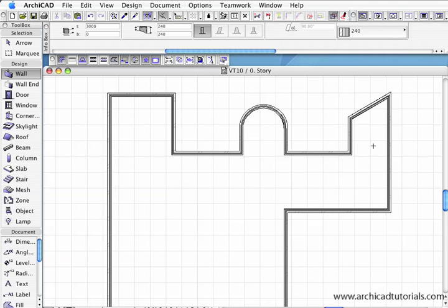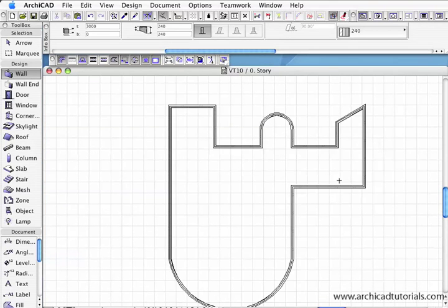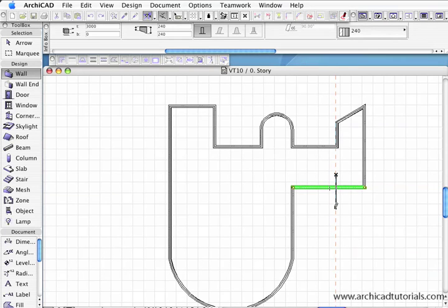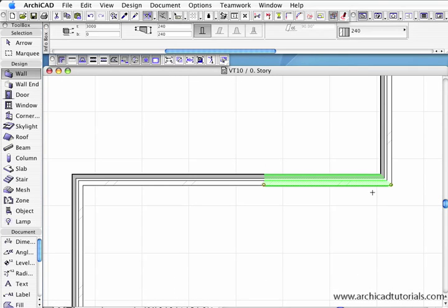Of course, you can split the walls and change them. If you wanted to change the wall type, you can just select the wall, click the axe tool, and draw a line through by left mouse clicking once and drawing a line through it, and then ArchiCAD is asking you which way do you want to split the wall, and click on the right hand side. At the moment we can see that wall selected, so now I might just change that to an empty fill.